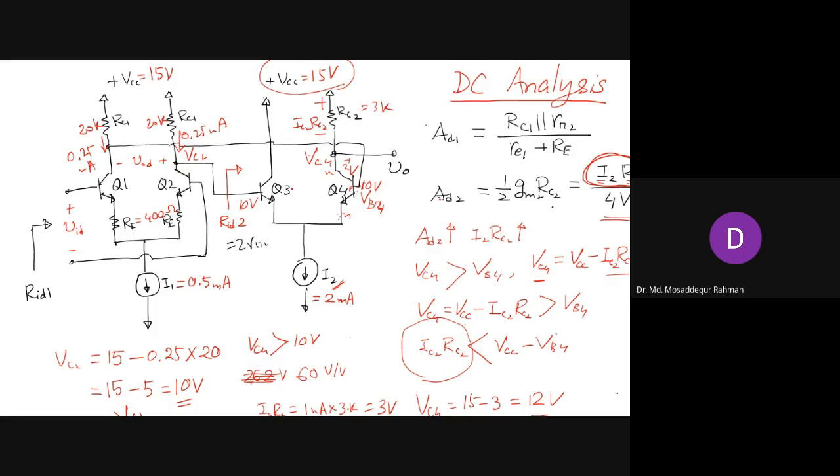If they cannot accommodate the magnitudes of your output signal, you won't get the output even if everything is correct. So it's not just the gain, biasing also has to be done appropriately so that it can accommodate the signal without going into saturation or cutoff.